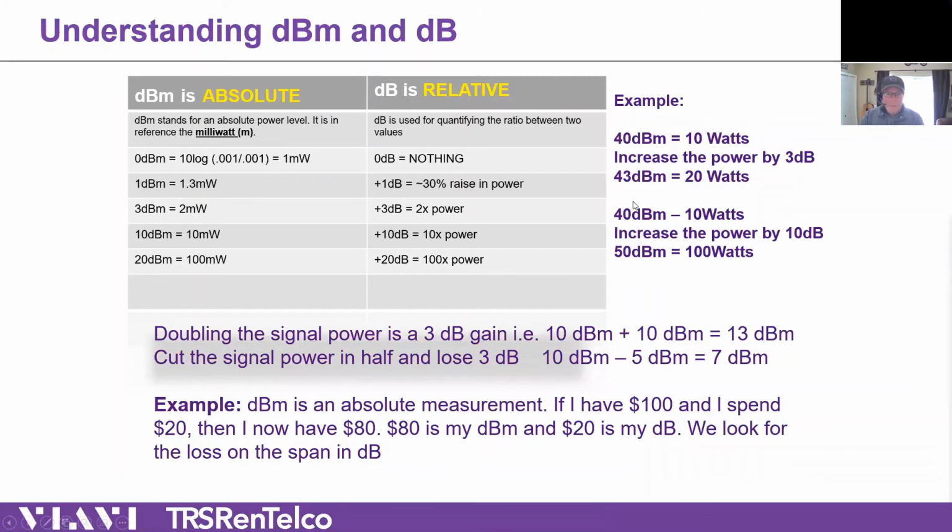Now, really the thing to remember when you think about qualifying your network, right? For those who worked on design of networks, you've got link budgets, and you've got power budgets, and you've got insertion loss budgets, all these things you work with, and there's calculators out there. If I were to take anything from this presentation, it would be this page right here as what do I need to know if I'm building a network or testing a network, right? And it's the absolute value of our case of doing decibels versus dBm, or decibels to a milliwatt, right?